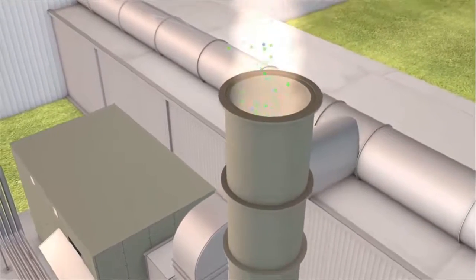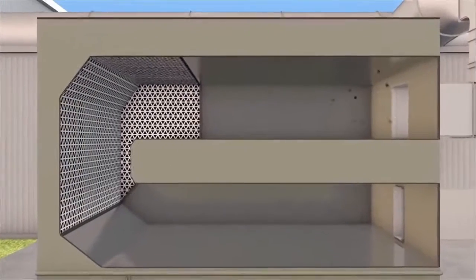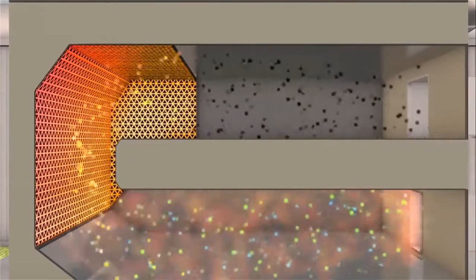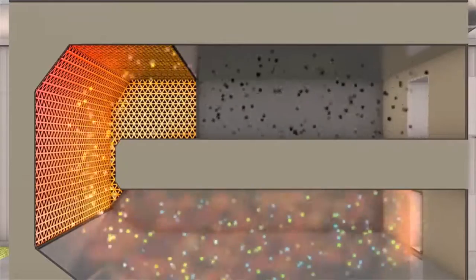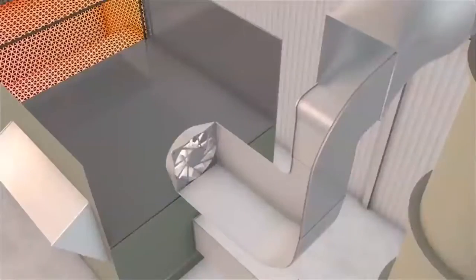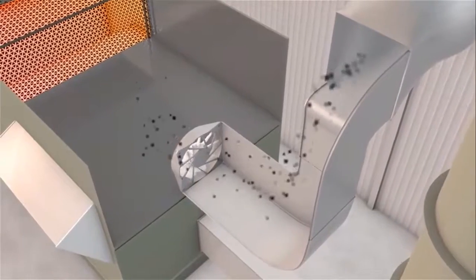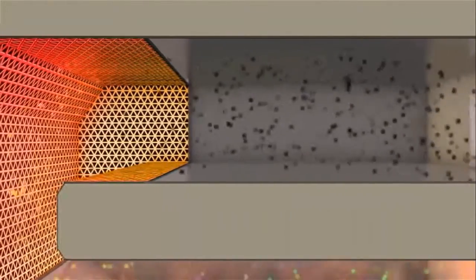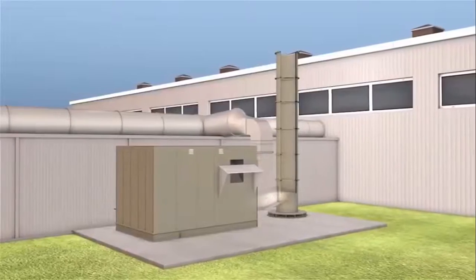It all starts with the chamber, which houses the heating element to burn the VOCs. The chamber is heated to a set point temperature of approximately 1500 degrees Fahrenheit. Once the set point temperature is reached, the fumes are brought into the chamber through a system fan. All VOCs present are oxidized and are broken down into carbon dioxide and water vapor, which carry through the system and out the stack into the Earth's atmosphere.